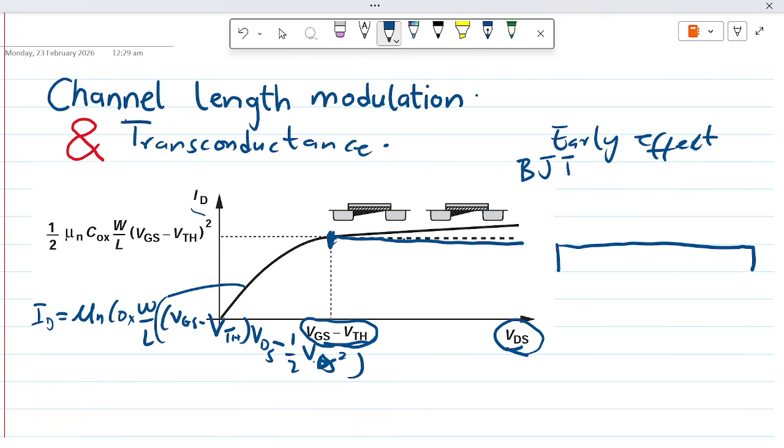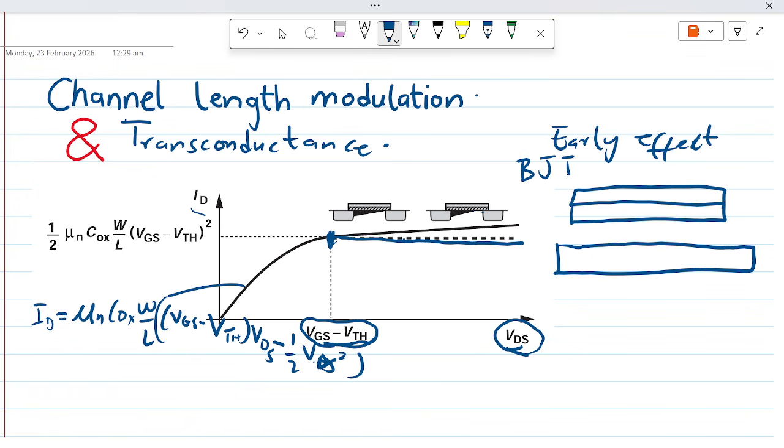Assuming this is my channel, with a gate, okay, that wasn't really well drawn. So assuming this is a channel, I have the pinch off here when VDS is equal to VGS minus VTH.